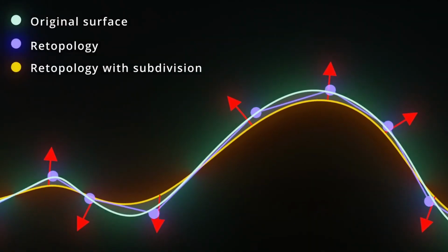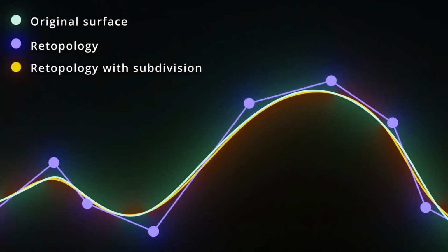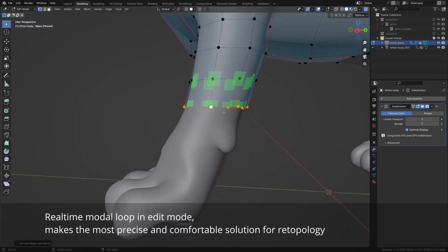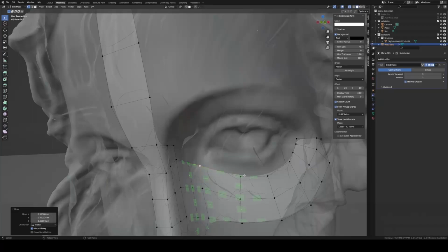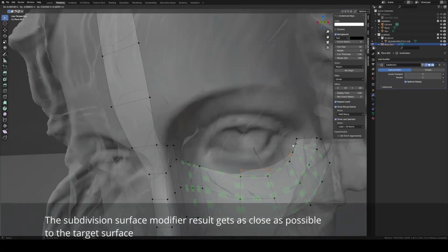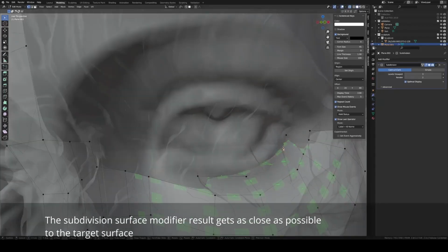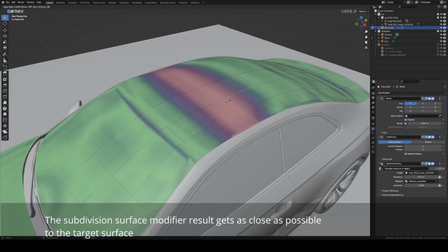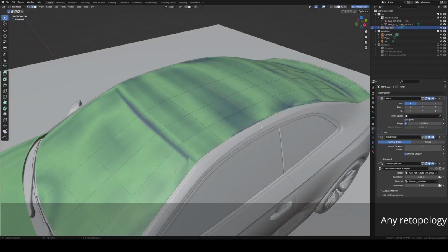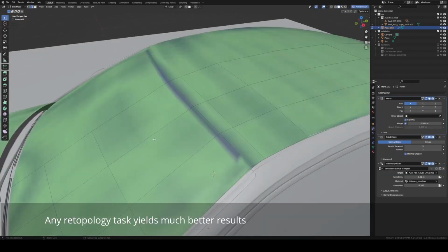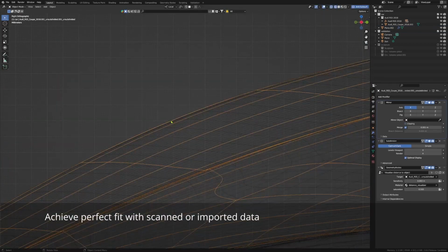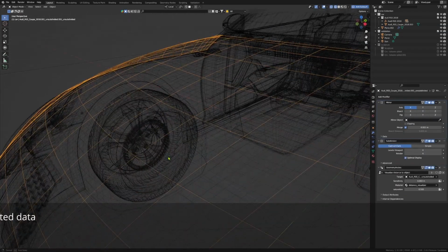First, inverse subdivision snapping, which is all about precise mesh adjustments and seamlessly transitioning into live mode for real-time modeling. Secondly, users can now with ease control neighboring levels and iteration settings, which can ensure accuracy during edits. In addition, the single-step operator simplifies complex tasks with customizable iterations, smoothly transitioning into unsubdivide, which restores original low-resolution meshes from the subdivided one, which I think can be useful.